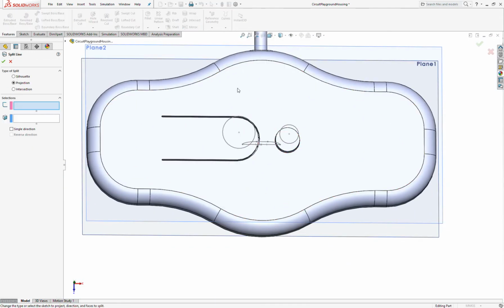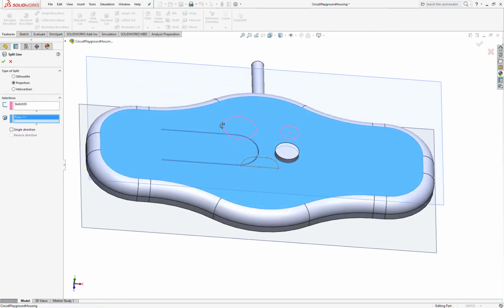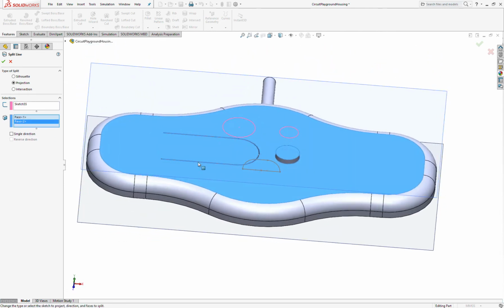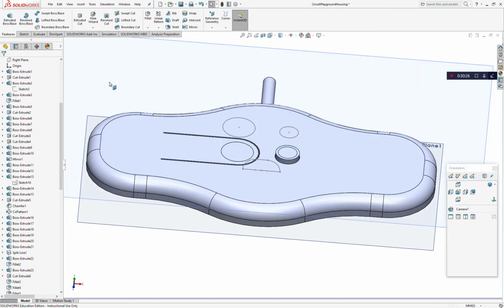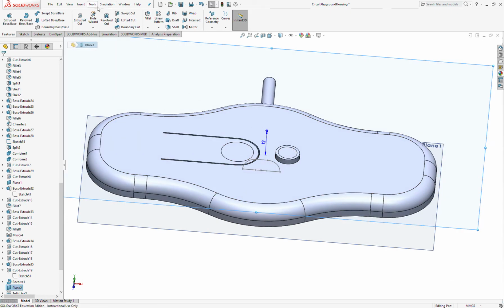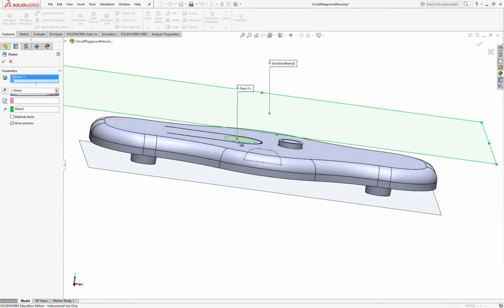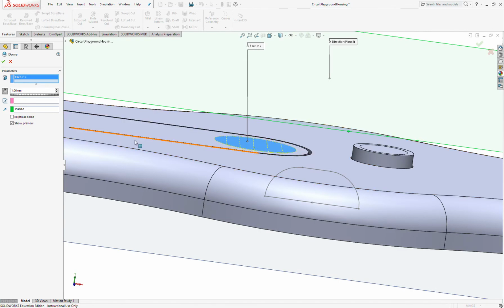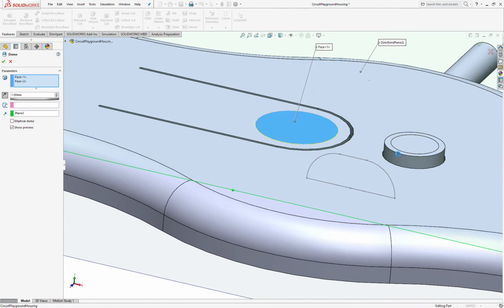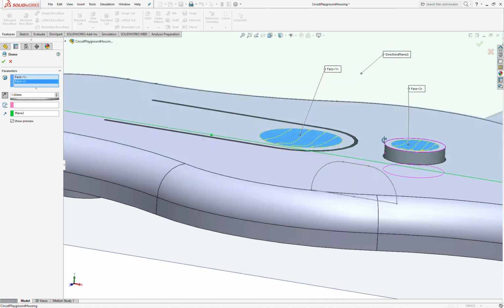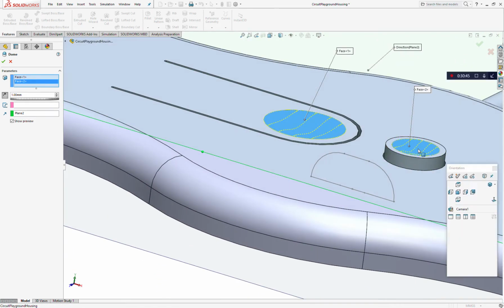We're going to do curves, split line, this guy onto this surface and that surface. So we now have those surfaces split. We can come in with an insert features dome. In this case, we're going to dome this one in. I think we'll do both in. I don't know if it'll let me do. There it goes. Ooh, but that one looks weird.